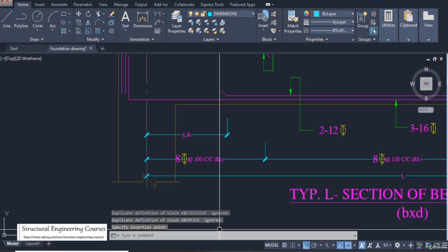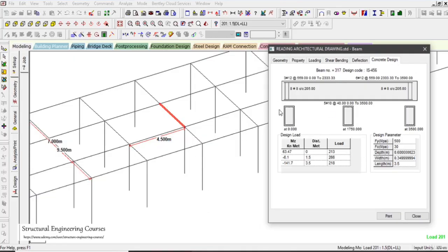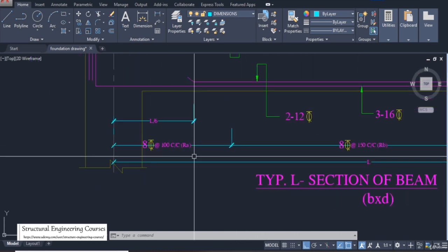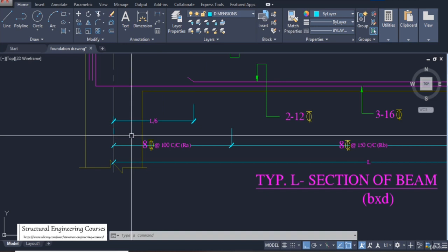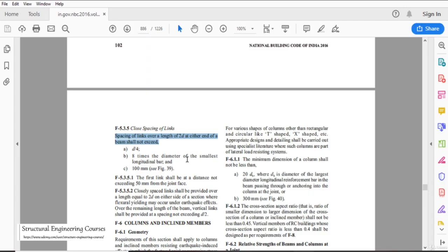And if we see the static requirements, here we can see that the reinforcement requirement is very less. That is only 8 dia at 200 mm center to center, whereas in this case it is only 8 dia at 165 mm center to center. So this 150 mm spacing is lesser than all of these. So in simple words, this spacing is most of the time governed by this particular clause only.